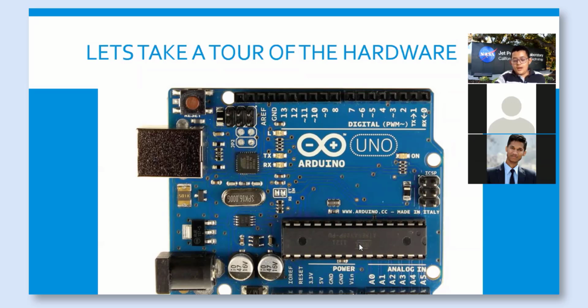the microcontroller. One of the great things about Arduino is that you can plug it into your laptop or computer and then power the project. But if you don't want that, and that is not necessary, you can use the DC jack over here. You can provide 5 volts to 12 volts over here and it will power the circuit.